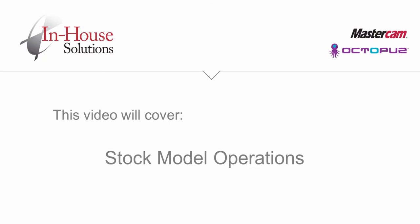In this video, I'm going to explain what stock model toolpath operations are and how they can be created. In the first example, you will learn how to use a stock model to generate REST machining toolpaths. You will also learn how to use the stock model to check the toolpaths in Verify.